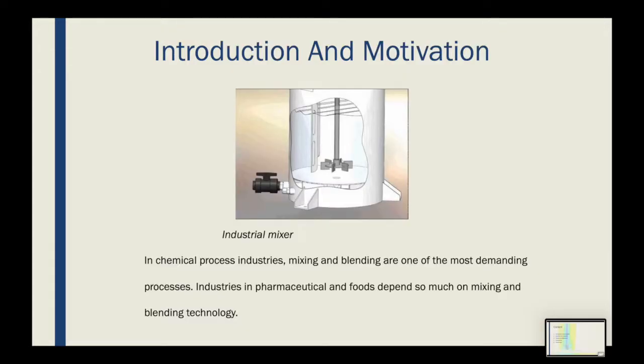Mixing. The primary aim of mixing is to improve the interfacial mass transfer rate in the vessels, which is related to interfacial area between phases, volume fraction hold-up, and bubble, droplet, or particle size distribution. This is why the characterization of the phenomena during agitation is an important field to study, because it can improve the quality of the products or can prevent damage of the reagents.